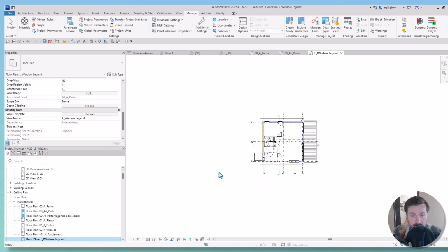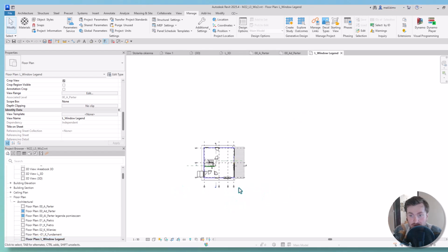Okay, now we need to decide on the space where we will create those objects. You think that maybe this is a little messy, like we will have other objects floating in space, but that's not going to happen because we will be working in the future phase and all other views are still under New Construction. So those objects will never collide. So it's good to have them separate.